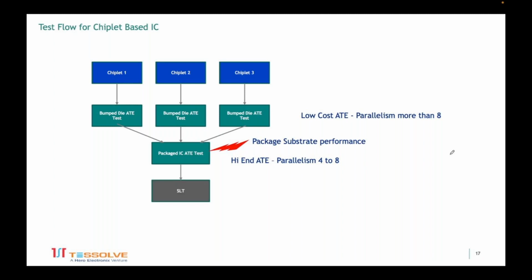And as for the site, for the reasons that we talked about, SLT could maybe be required, definitely, after you do an AT test. With a single-site AT and SLT environment, you could use the existing handler for the new product as a safe launch. But when you go to volume, you need a highly parallel SLT solution to run on a proper SLT handler, and we ship to the customer.